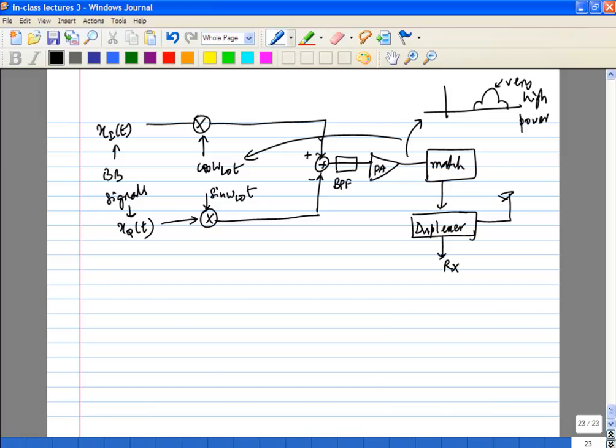When you are trying to transmit so much power, the PA spectrum, either through electromagnetic coupling, or through a common supply if they share one, or through the substrate if they are on the same chip, you could see what is called PA pulling. This modulated spectrum will corrupt your pure sinusoid and it will give you a very noisy system, a noisy LO.